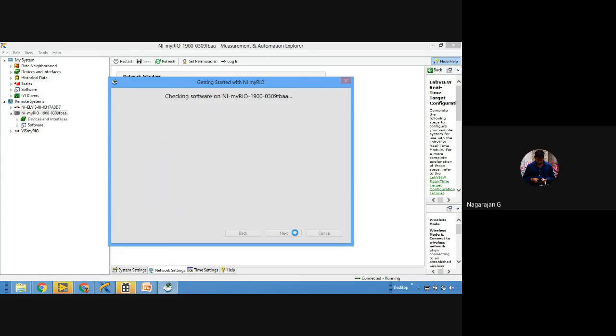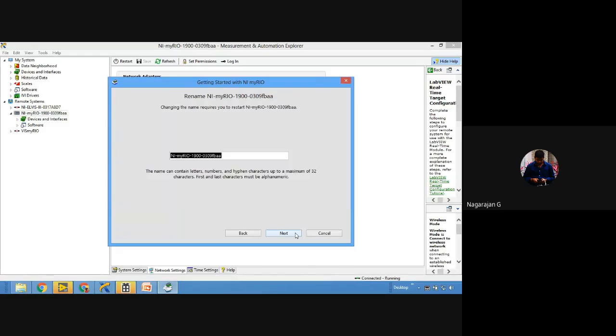Now, whatever you have learned till now, you would directly open LabVIEW, select File, New VI, and start to develop the code. But once you start to work with RIO based hardware, you should not directly create a VI, because a VI created directly will run on your system only. Whenever you want to do anything with any NI RIO based hardware, you first need to create a project.